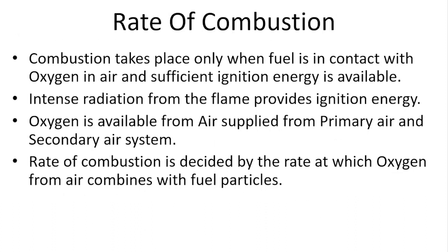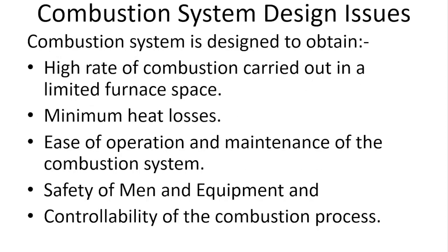The rate of combustion. Combustion takes place only when the fuel is in contact with oxygen in air and sufficient ignition energy is available. Intense radiation from the flame provides ignition energy. Oxygen is available from air supplied from primary air and secondary air system. Rate of combustion is decided by the rate at which oxygen from air combines with the fuel particles.